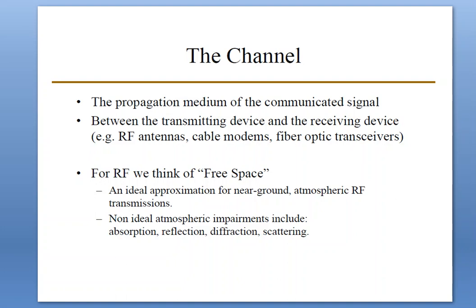Coming to the concept of free space. The concept of free space assumes a channel free from all effects on RF propagation such as absorption, reflection, refraction or diffraction. If there is any atmosphere in the channel, it must be perfectly uniform and meet all the conditions.